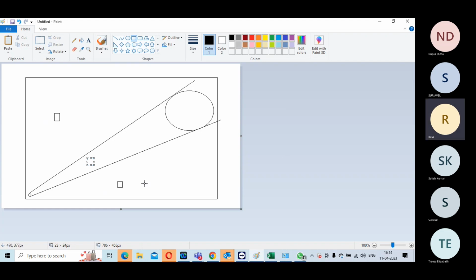Zigzag forms, and offset only. Correct. Then what it will do? It will construct like this, right? So then you will get a good clock tree. Okay. So similar, something like this. So you'll get a good clock tree within the line of sight. So you have to make sure the clock muxes, the clock replacement cells are all properly taken care of, so that this one logic is actually in a good control scenario.